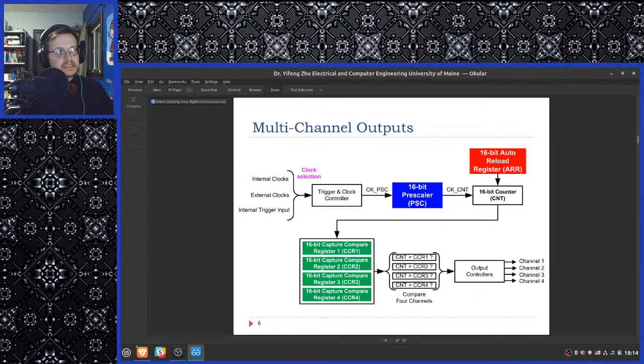So it really makes sense to have one and then scale that signal depending on what you need from it. The other thing is most of the time you won't be adding your own oscillator to the setup. The board that you're working with, be it an Arduino or a Raspberry Pi or whatever, is going to have an oscillator. Sure, you totally could buy an oscillator with the frequency you want and plug that in and everything will work. But prescalers are cheaper and smaller.